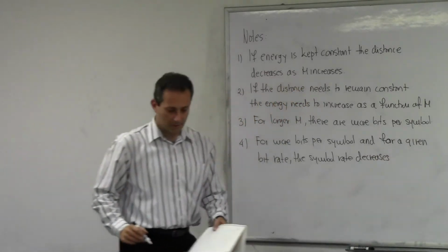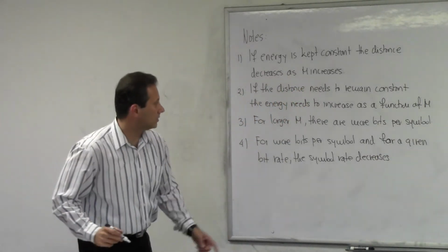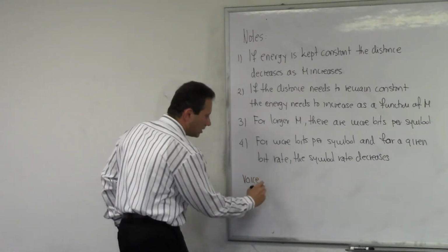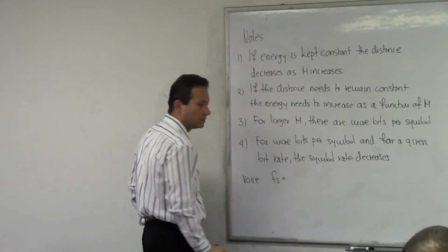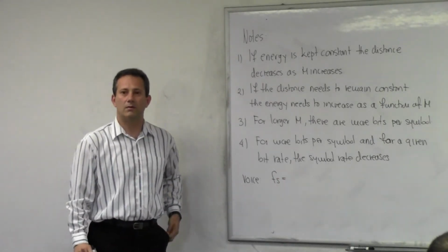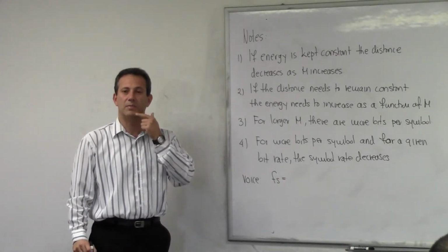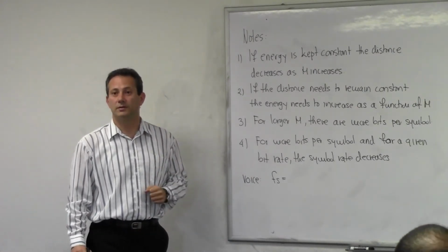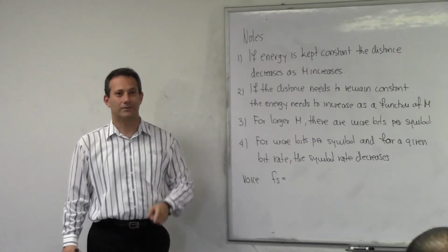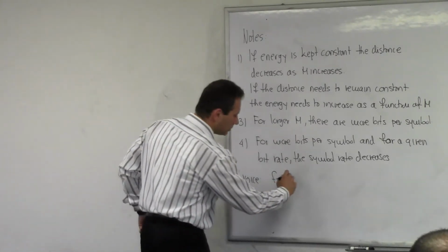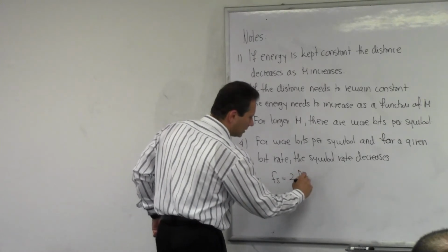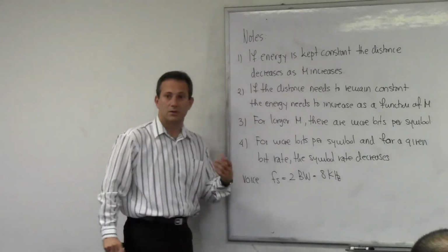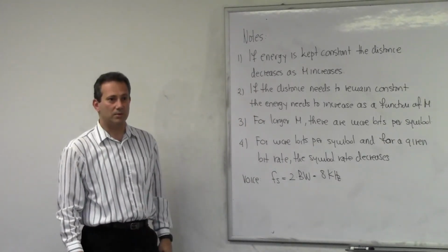Let me give an example here to explain what is happening. Let's say we're working with voice. What is the sampling rate for voice? How frequently do we sample voice? What is the voice band? Telephone voice. 4 kilohertz, right? So it's 2 times the bandwidth, our sampling rate. So it's going to be 8 kilohertz, right? 8 kilosamples a second, 8,000 samples a second.